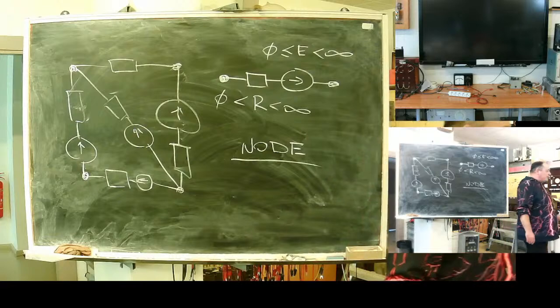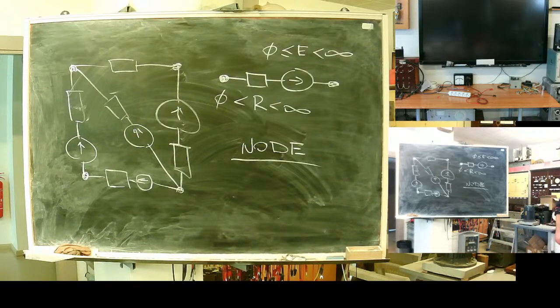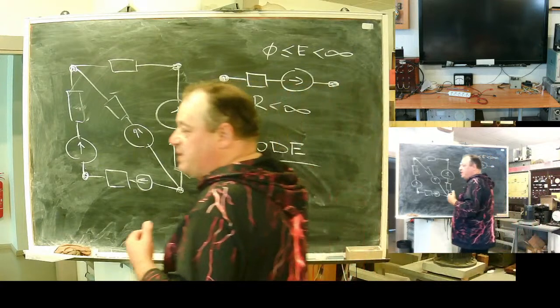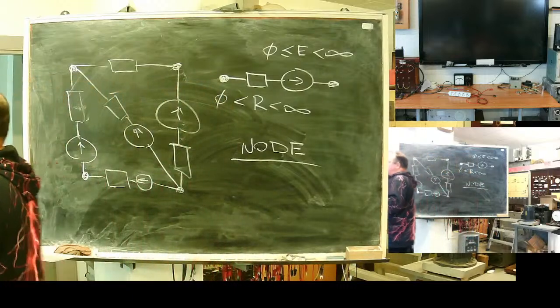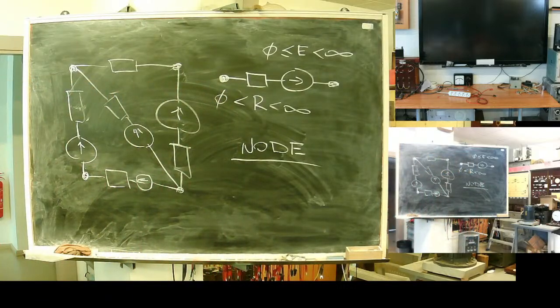In reality, it's not so easy. Sometimes my reference point will be true ground, true earthing point. On other cases, it's a bit more tricky. See that the requirement for a reference point is that it should have a constant voltage. Not zero, not ground, only constant.